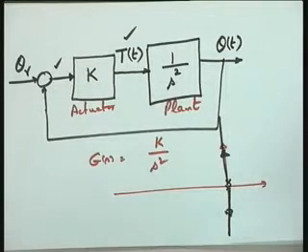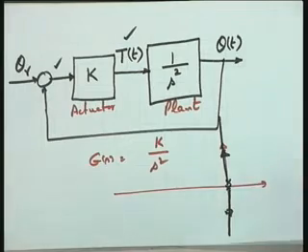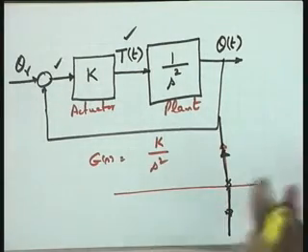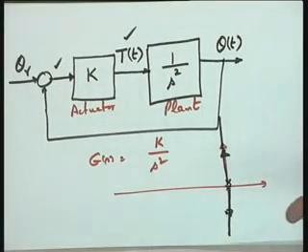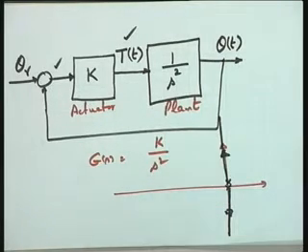So before you go for it, I am going to illustrate the phase lead compensator, but naturally, given a situation, you will have to take the decision whether to go for a phase lead compensator or a phase lag compensator. The decision making problem is also the problem of the designer. So at this point I take a decision that probably the phase lead compensator is the choice, because a phase lag compensator has to improve the steady state accuracy, and steady state accuracy improvement is not required in this case.